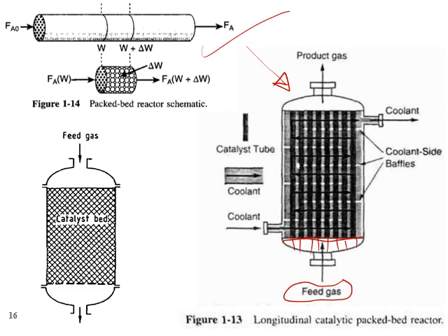Of course, if you need to control the temperature, you can use the shell for that. So you flow a coolant here, and the coolant flows in this direction. Why this direction? Because I have baffles, just like the shell and tube heat exchanger.